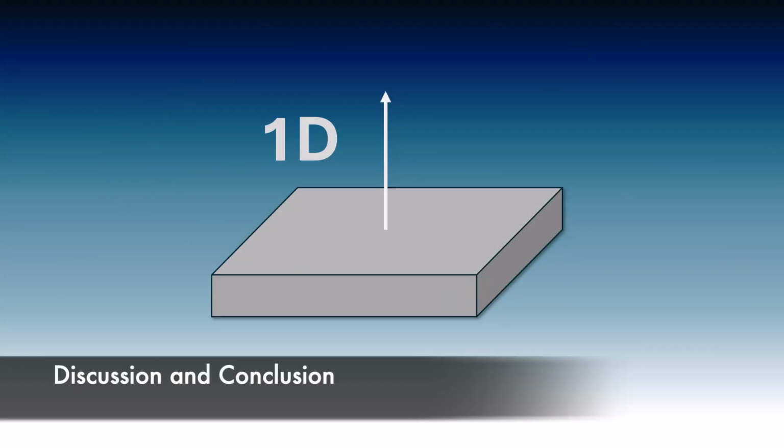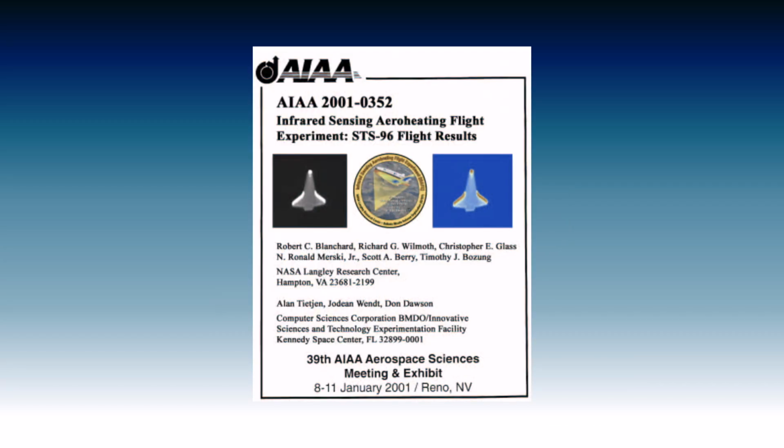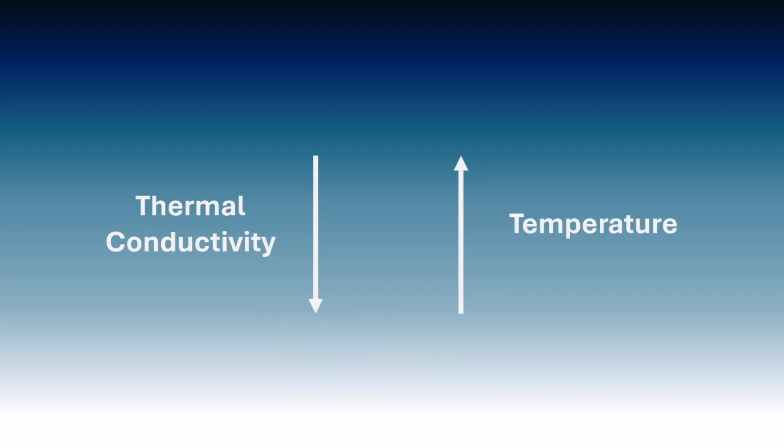The model's limitations include considering only one-dimensional heat transfer and using data from a single space shuttle re-entry, potentially requiring a safety factor for future missions with varying temperature distributions. Additionally, the assumption of a perfectly insulated inner boundary is unrealistic in a space shuttle. The model assumes constant material properties, disregarding their variation with temperature. This simplification affects the predicted temperature at the insulated boundary.